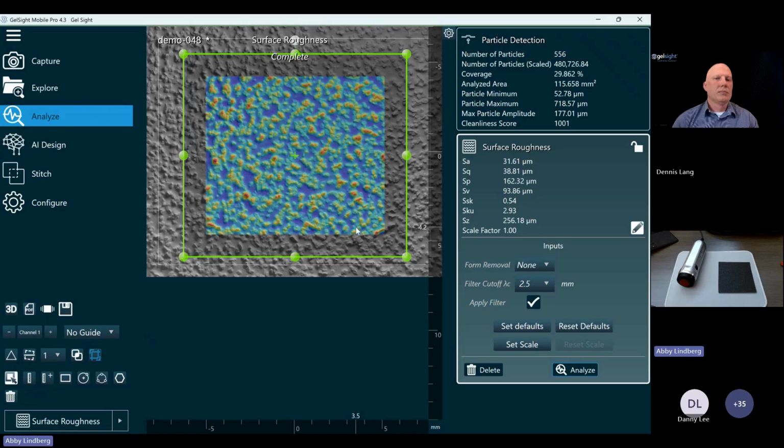And so this can be challenging because of the different materials, but also the geometry of those particles. Sometimes these rougher surfaces are actually going to be a lot more challenging for these optical systems because of the numerical aperture required for the resolution to get to these, but then that also limits the angles that you can measure on the side of these. So the structure of these having steep angles can be typically challenging for some of these optical systems too. And with needing a larger field of view to measure